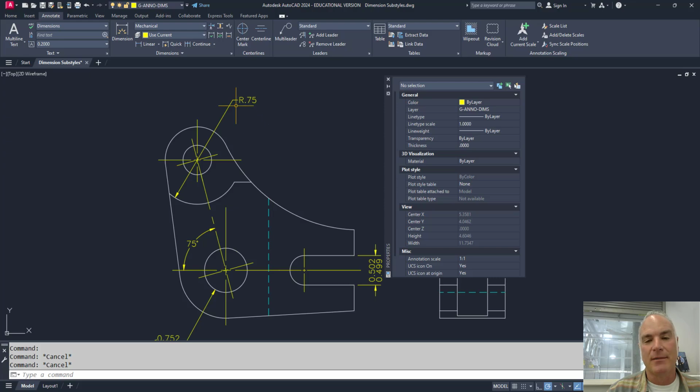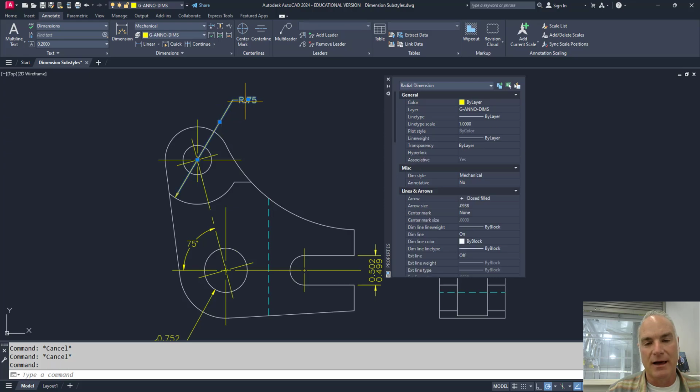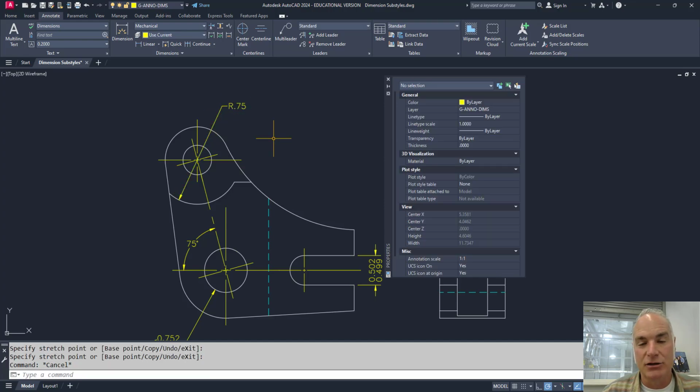And now notice that my dimension line, that is, the leader goes all the way through. So it goes through that point, and no matter which way I have this point, it goes all the way through there. So that's probably the easiest way to change that. Now, there's lots of other ways. I encourage you to go in and create your own dimension styles and experiment with it, because you can save a lot of time with your dimension style manager by creating substyles.